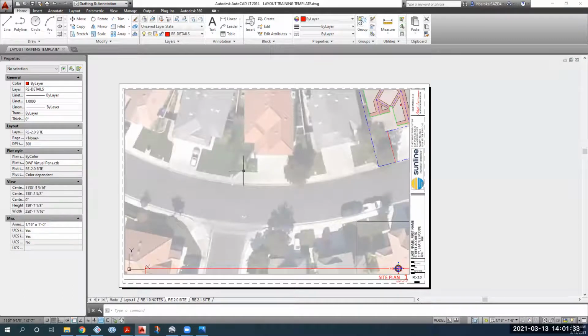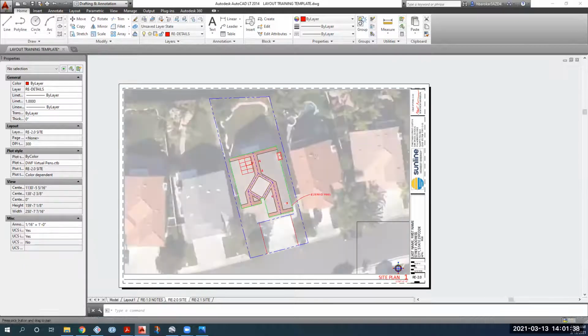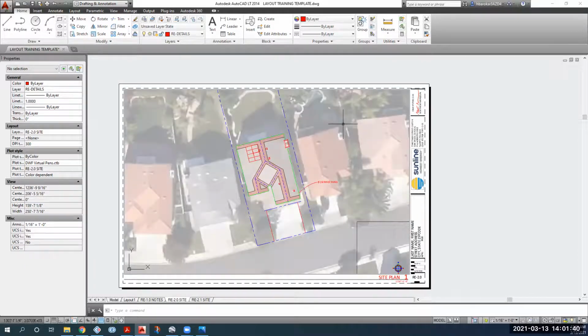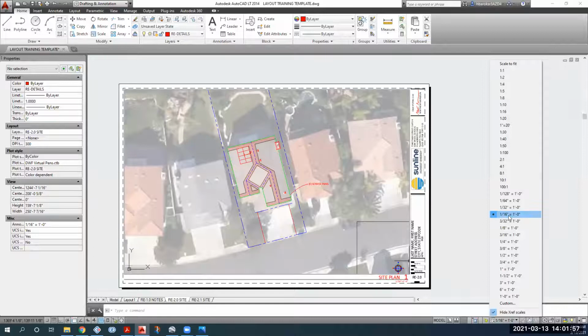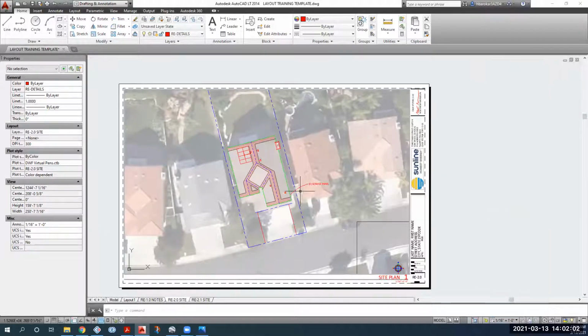This is where things will be automatically filled in my drawing sheet through this thing called a viewport. A viewport is basically the area on the drawing sheet that takes the view of a particular place in our model. So it's essentially like a wormhole to that place. And then I want to make sure that my scale is set to 1/16 of an inch equals 1 foot. So 1/16 of an inch on the paper is equal to 1 foot on the map.